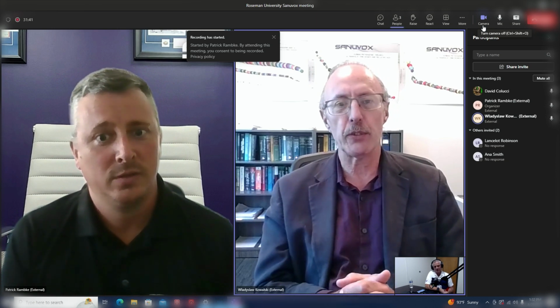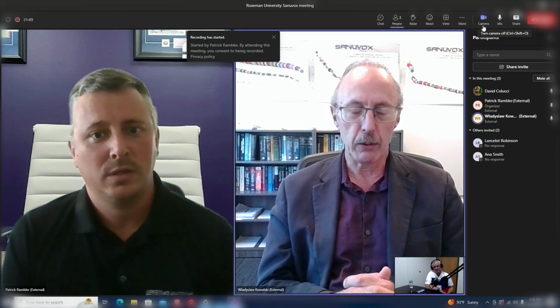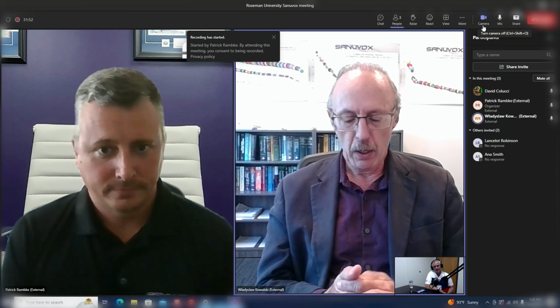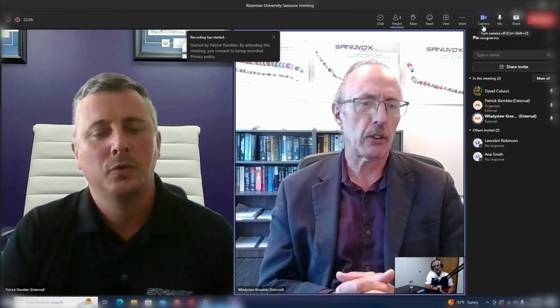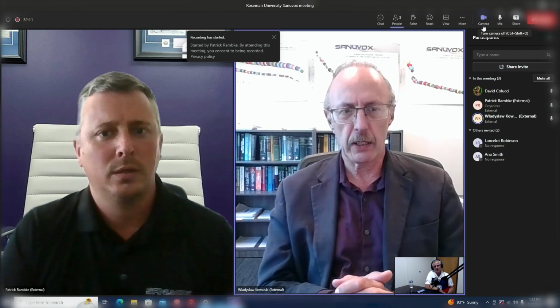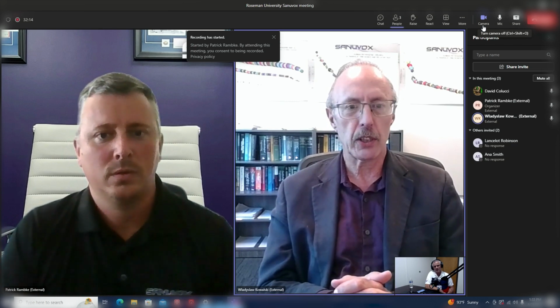Okay, we use basically two types of lamps. One is the low pressure UVC lamp. It emits at 254 nanometers. Also, we sometimes use medium pressure UVC lamps that emit at a more broad band, but they include 254 nanometers. And also medium pressure lamps produce a little ozone, whereas the low pressure lamps produce no ozone at all. And the far UV lamps that are in use have a tendency to produce ozone. They emit about 230 or 222 nanometers. They produce some ozone, but there are ways of controlling the ozone. There are systems that can reduce the ozone levels.